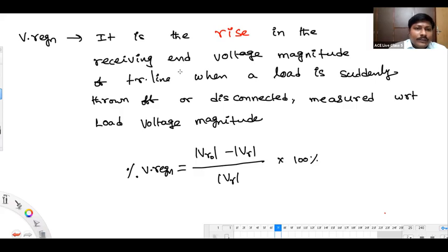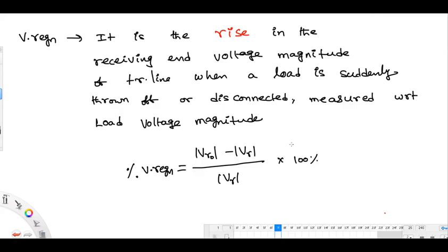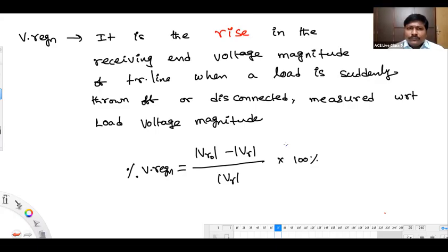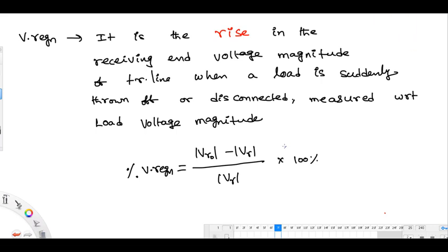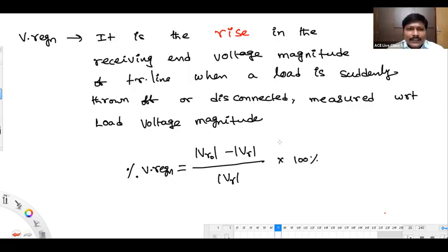Yashwant. Tell me, Yashwant. Sir, previously you took a 150-kilometer line in a 100 bus system, and you told we use pi model here because we don't want extra nodes. Sir, in a 100 bus system, each bus can be noted as one node, no, sir? One node, yes. So why not use 100 T models in a cascade, like in a distributed system?